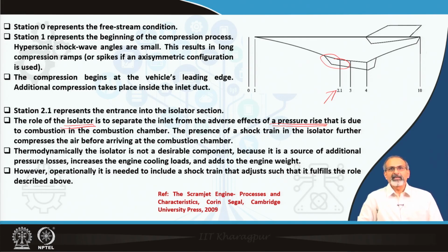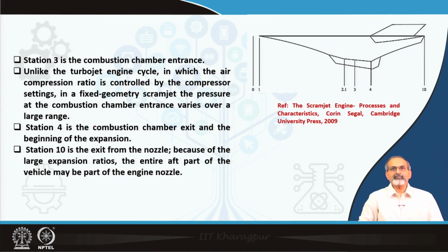Though thermodynamically it is not a desirable component, because it will lead to further pressure losses and increase the engine's cooling loads. It also adds to the engine weight and reduces its reliability. However, operationally it is needed to include a shock train that adjusts such that it fulfills the role which we described just above. Station 3 is the combustion chamber.